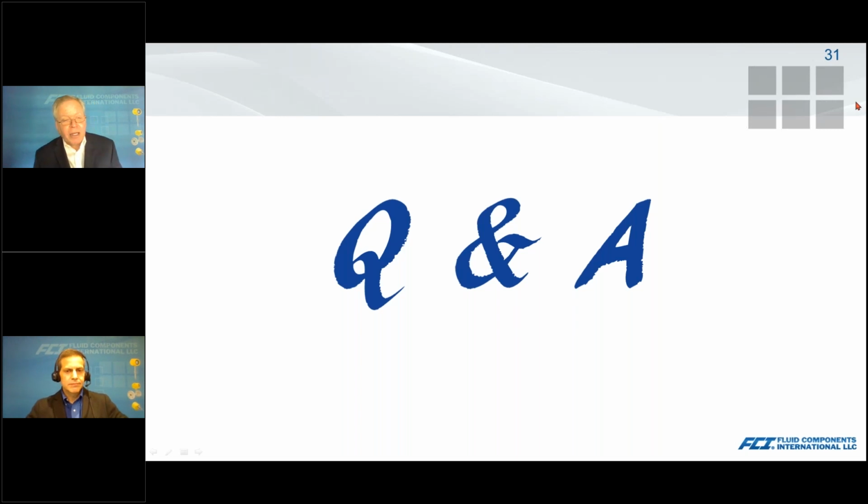Okay, thank you. And we do have a couple more, Art. We'll move on to the next question: do most flow meter manufacturers use actual gas calibrations? That's a great question. Experience has been that not every manufacturer has the capability to do an actual natural gas calibration in-house. A lot of times you might see an air equivalency used with an equivalency factor applied to it, which will have some additional inaccuracies to it.